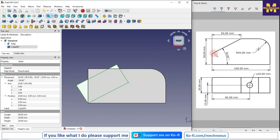If we calculate this distance here, it comes to 21.13. You can easily calculate it by hand sketch by drawing a triangle. So this is 21.13. So now we will see our UCS. Here the Z direction is here, so we have to move our cube by 21.13.